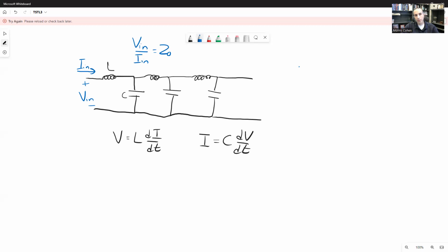And you've also got this voltage over here that's established. Now this Vn has to go through one of two places. It can either appear across the inductor or it can appear across the capacitor, right? We can apply Kirchhoff's voltage law: if I take this branch like that, I've got to get the same voltage drop Vn. So I've only got two choices where that voltage can go.